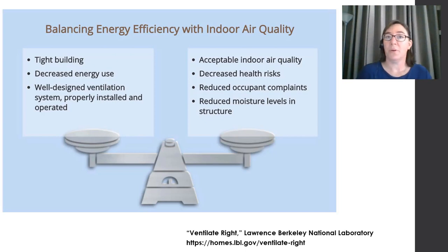In the 30, 40, 50 years since then, we have learned that you need to balance your energy efficiency with your indoor air quality. We still like to build our buildings tightly enclosed with decreased energy use, but you need to also include a well-designed ventilation system. And therefore, you can achieve acceptable indoor air quality, lower health risks, reduced moisture levels, and finally, reduced occupant complaints.